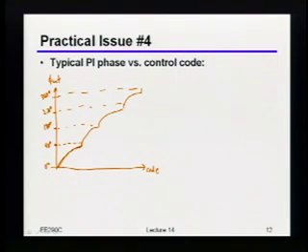So now, here's the fun question. What in the heck causes that? Why do you get these jumps like this? The mux has to switch. Ah, the mux switched. Why is that bad? Why does that cause a problem? Well, you go back to 0 on that funny looking plot. That's true. You do go back to 0. By the way, there is a way to make this go away. But why is it that changing the mux code does something funny to the phase of the output?